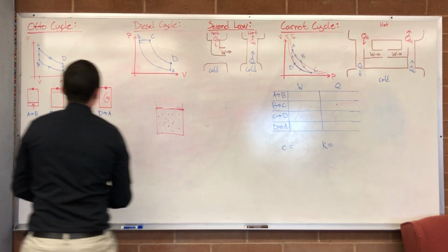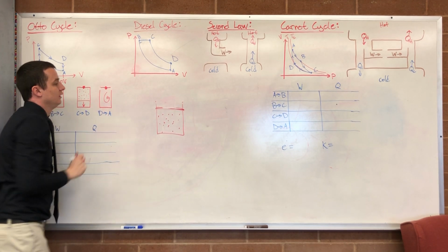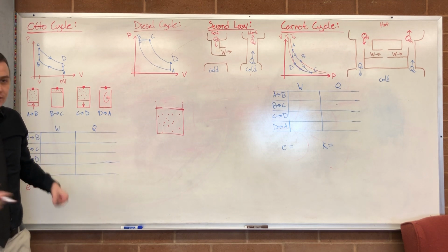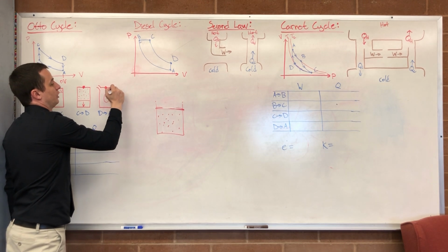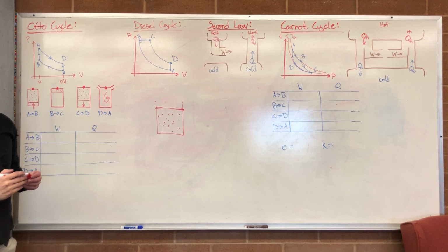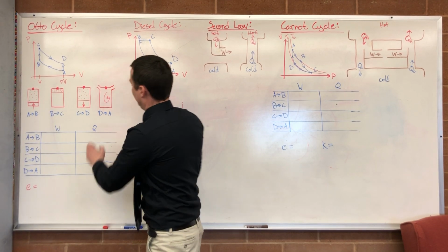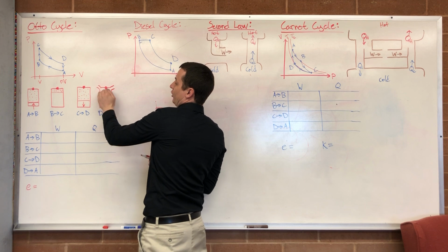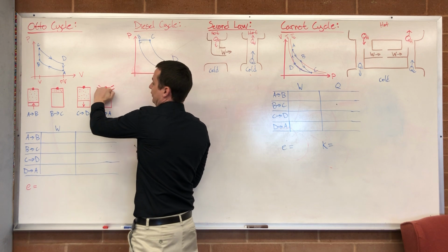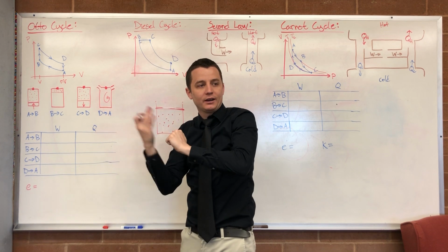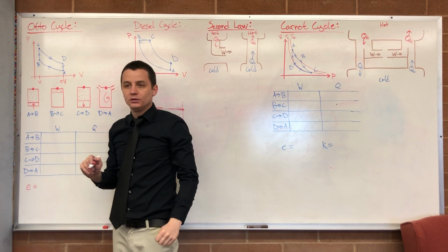your piston, there's actually two little valves at the top that can open and close. This one is hooked up to your gas fumes, so this is where you can let gas fumes in from. This is hooked up to the air outside. So what happens is, this one's closed off, the piston goes up and pushes all the hot air out, and then we close this one off and let this one open as the piston comes back down, and it lets in air from outside mixed with gas fumes back in. And that's the exhaust. And that restarts the system.